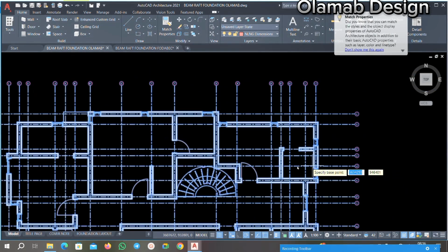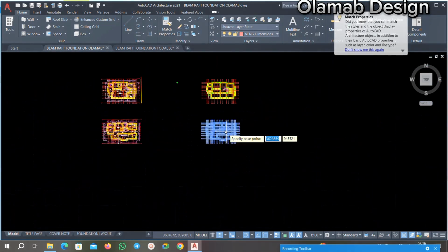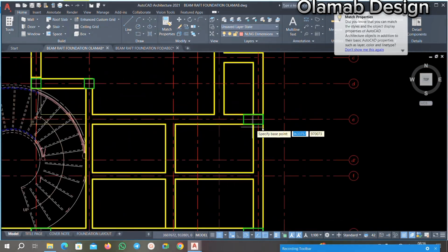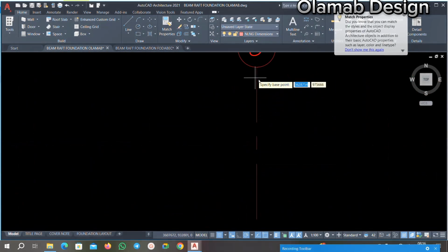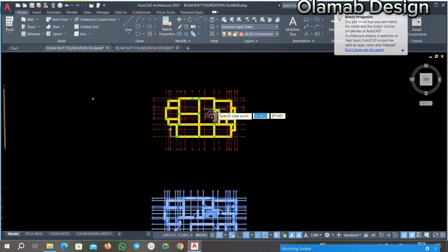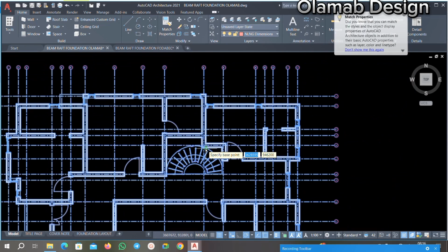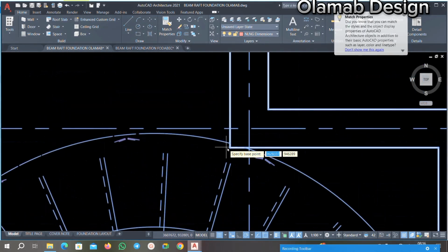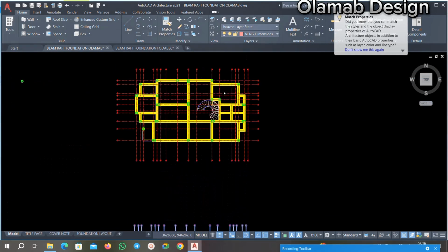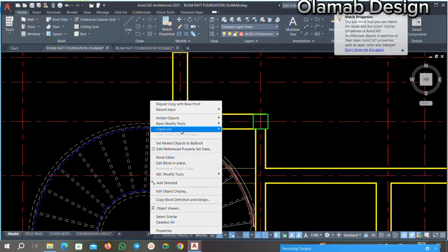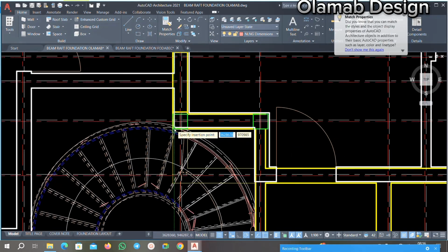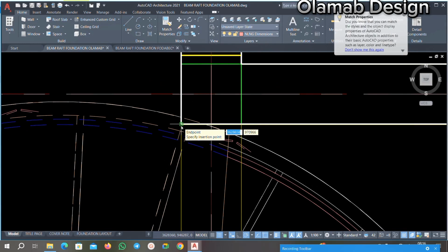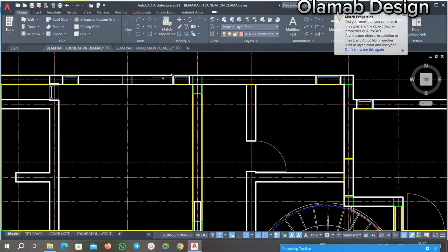If you look at this grid D now, grid D on 8, you see that this angle remains the same. You can just pick it from this angle here, that is grid D on 8, which is this point. You pick it from here, then you go to this place, right click and say paste under your clipboard, then you paste it at this point. You paste it here, can you see? Then you'll be able to see where there is a cantilever.